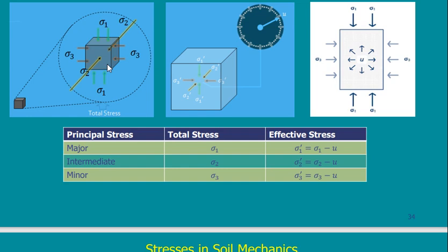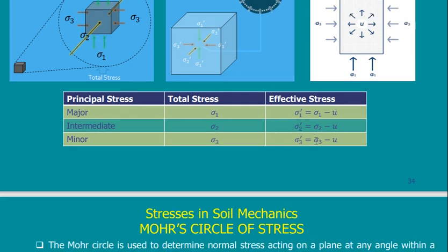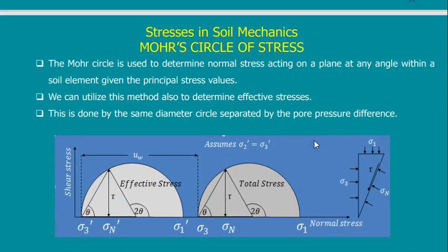So this is what I need to calculate for the soil, because soil that is squeezed and stressed will behave differently than another soil that is not that squeezed. So this is important for us in future studies to understand what is sigma 1, sigma 2 and sigma 3, what is water pressure, so what is total and what is effective stress. This is what is important here.